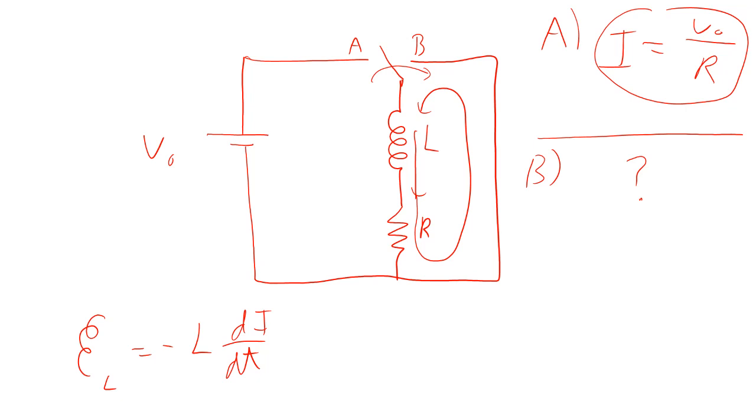We'll do that by imagining starting right up here at the X at the top and doing a Kirchhoff loop going around in a counterclockwise direction. If you do that, you've got the EMF on the inductor minus IR equals 0. The EMF on the inductor is minus L di dt.